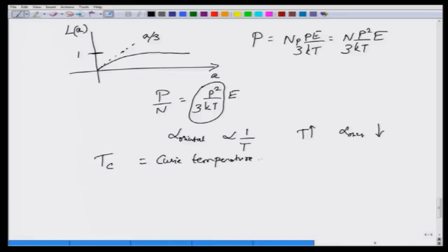There are certain dielectrics in which, when you apply an electric field and take out the electric field, the dipoles will not actually go away. Those are called ferroelectric materials. There are also materials which have some permanent dipoles already present. Those are called polar dielectrics. Non-polar dielectrics are those that do not have an inbuilt dipole. If you apply an electric field, dipoles will be induced, but they will go back when there is no electric field. Polars have permanent dipoles. Ferroelectrics have this nature of staying aligned with an electric field.